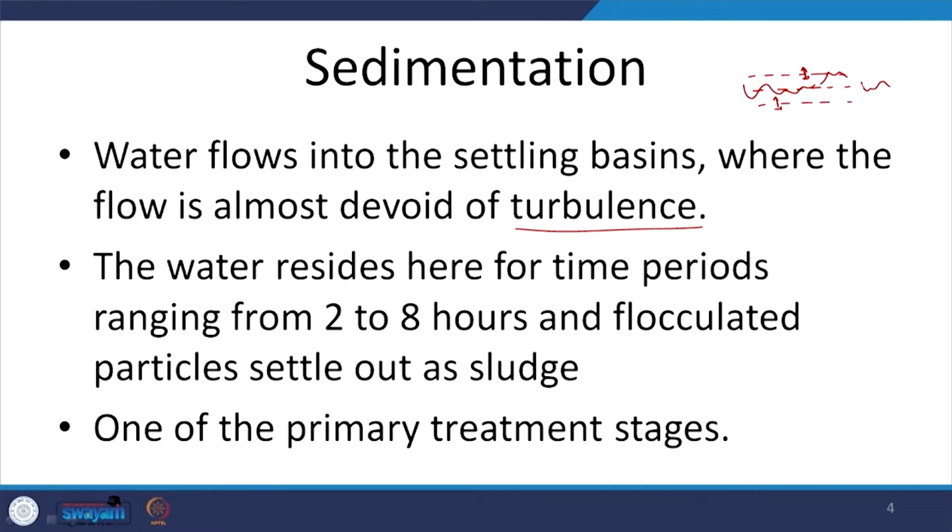Typical retention times are from 2 to 8 hours, and the flocks or particles settle out, and that is what we refer to as sludge. Let us say this is my sedimentation basin, so the bigger particles are going to settle down, and this settled out fraction we are going to call sludge.